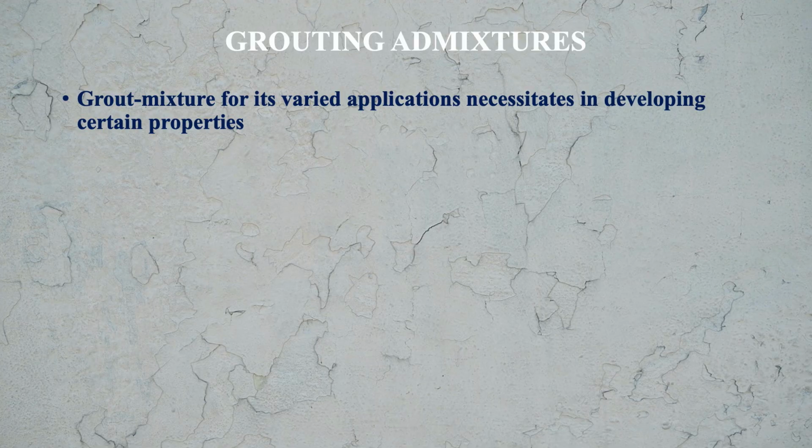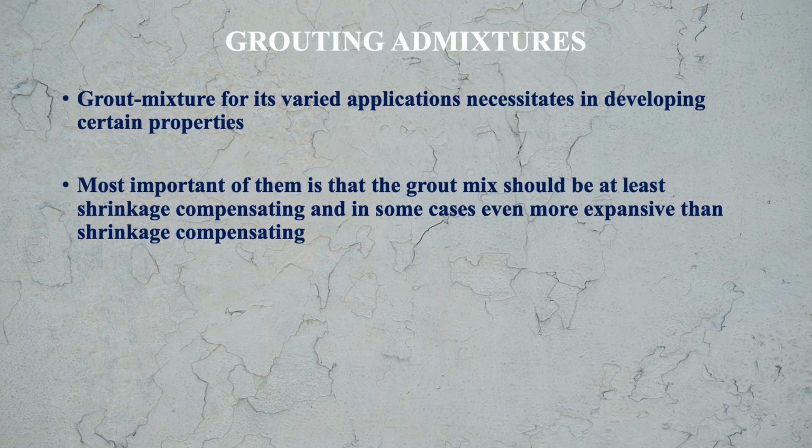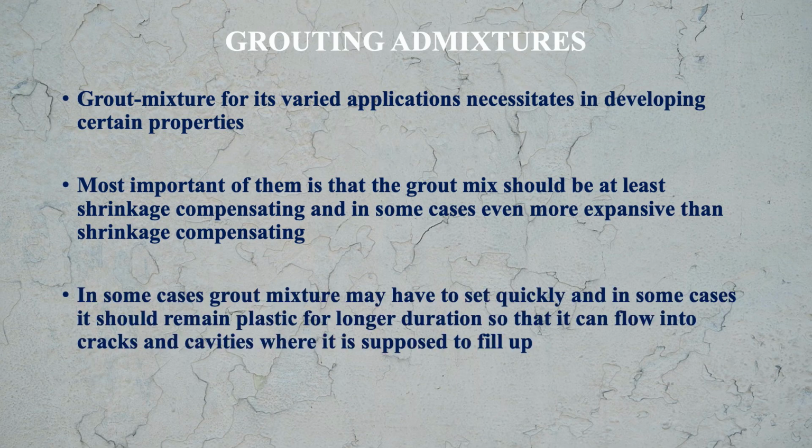Now let us see grouting admixtures. Grout admixture for its varied application necessitates developing certain properties. Most important of them is that the grout mix should be at least shrinkage compensating, and in some cases even more expansive than shrinkage compensating. In some cases, grout admixture may have to set quickly, and in some cases it should remain plastic for a longer duration so that it can flow into cracks and cavities where it is supposed to fill up.